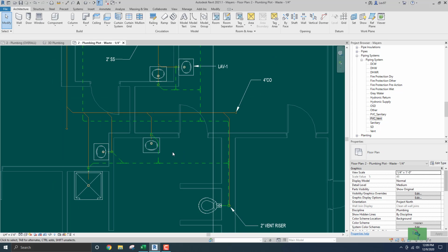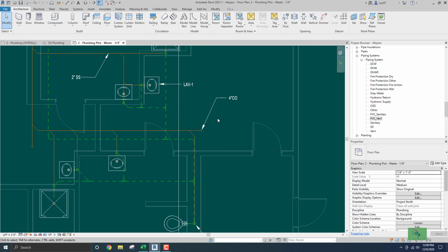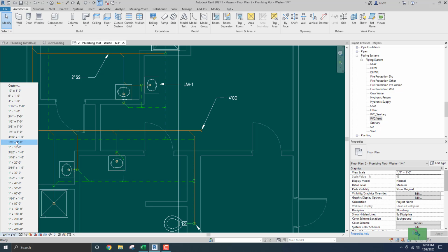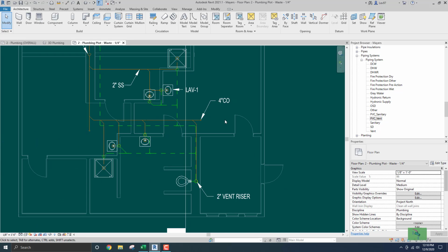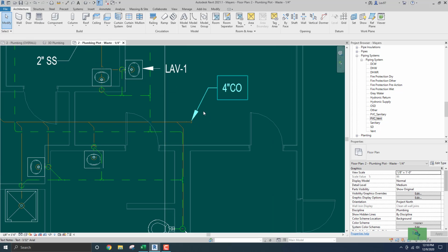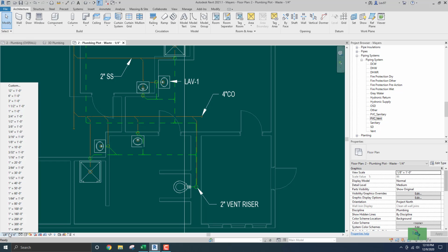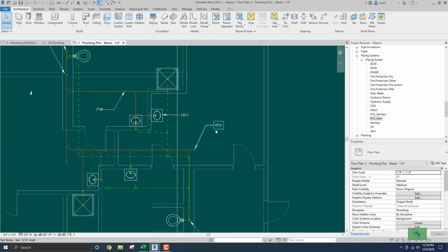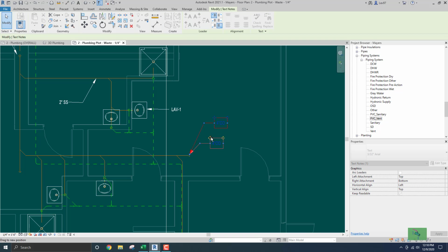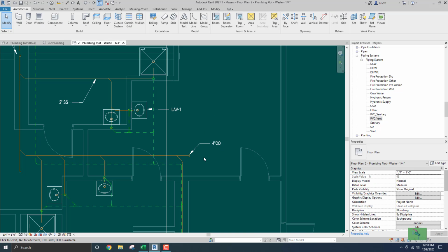So yeah, it looks like the reason is, I was looking at my arrows and my arrows look big and my text looks big, right? And I was going to go in here and change these arrow sizes, but I realized that the scale is usually a 1/4. And I think that those arrows are a 32nd, which is what I want. Well, I realized the scale was an 1/8, but I need to change it to a 4th. Okay. Which is the correct scale for a document when you want to plot it, right, for an enlarged plan.